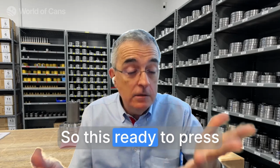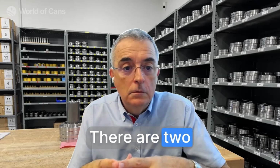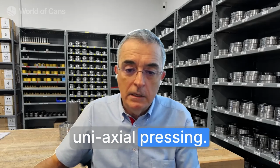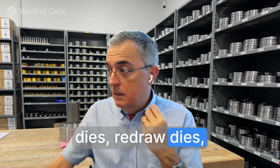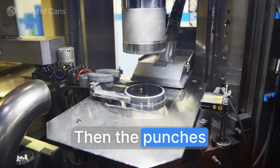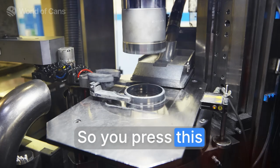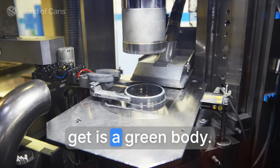So this ready to press powder is compacted. There are two technologies being used to manufacture can tooling. I will start with uniaxial pressing. One is used mainly for ironing dies, hydro dies, copper press tools. You are filling a cavity with powder, then the punches are going up and going down. So you press this powder with a controlled pressure, and then what you get is a green body.